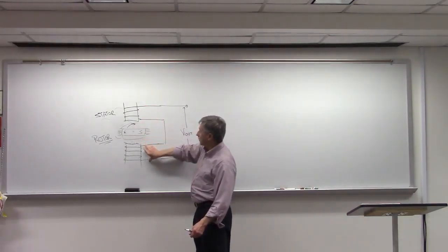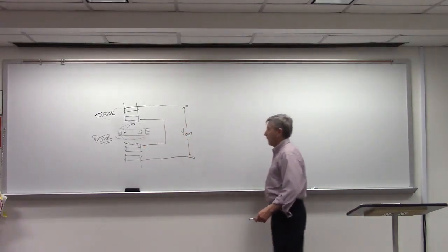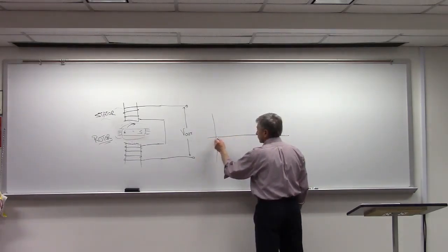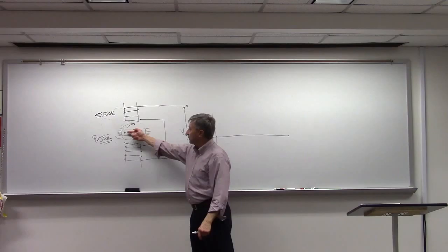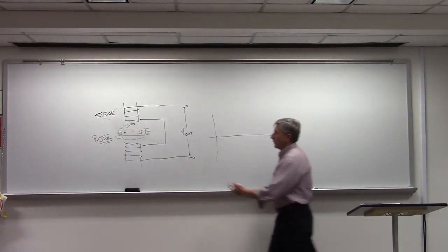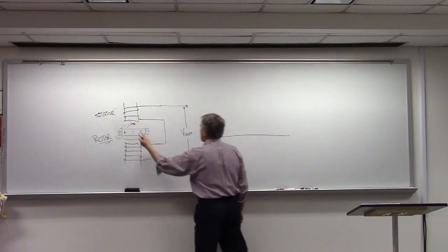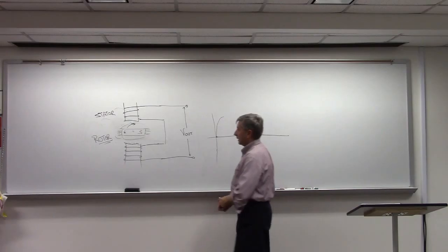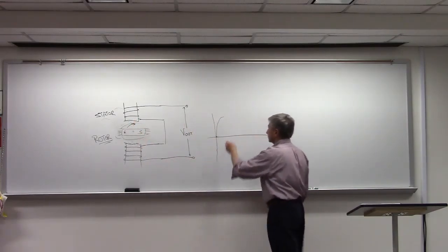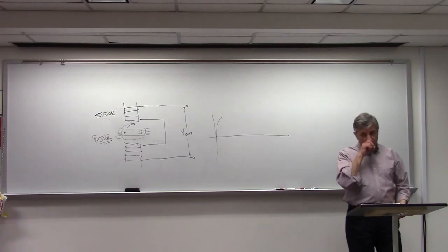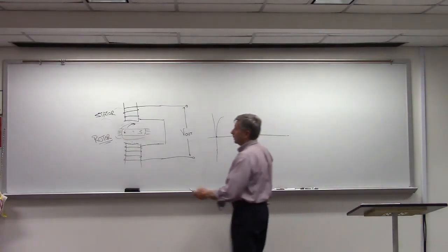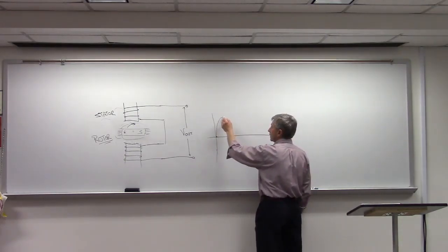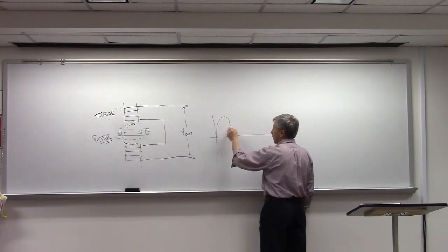These windings plus these windings equal V out. And so if I were to plot the output, I would start out in this position with virtually nothing. And as my rotor rotated clockwise, the voltage would increase, like so. It gets to top dead center, maximum voltage. All right, and now the rotor continues on through, and as it does, the output voltage begins to drop like so.